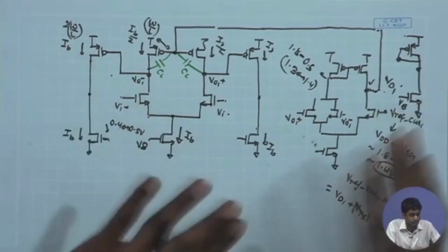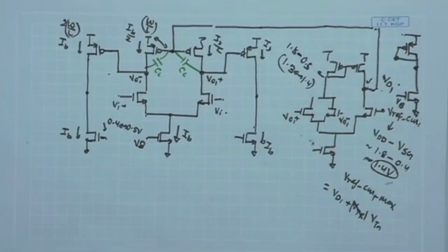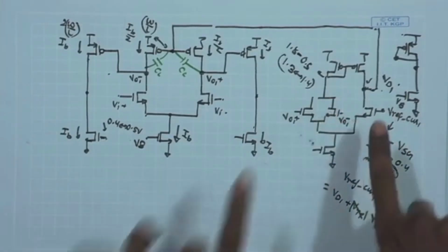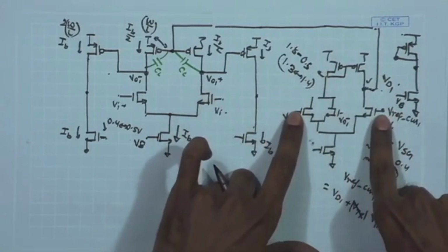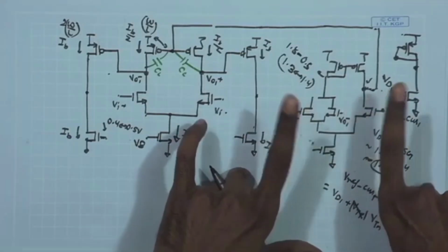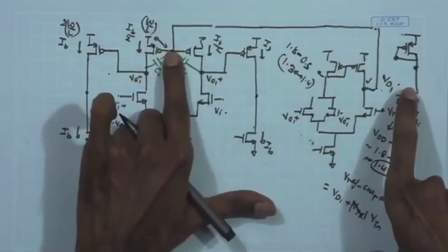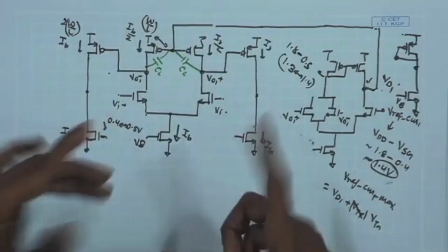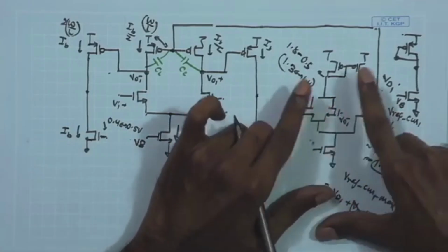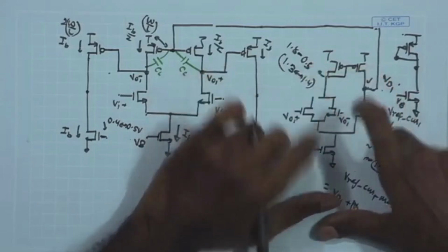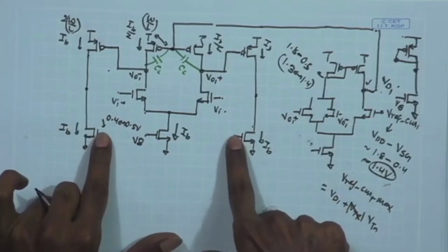And here we are discussing two separate common mode feedback loops and looking at some of the details related to biasing. Just like we concluded that this error amplifier with NMOS as input and PMOS as load is able to handle the required reference voltage, close to 1.4 volt, and is also able to provide an output voltage suitable for biasing this PMOS. Likewise, we also need to argue that a flipped topology, with PMOS as input device and NMOS as load device, will be required if we are constructing another common mode feedback loop for biasing these two.